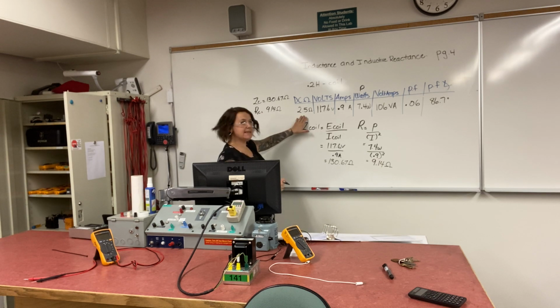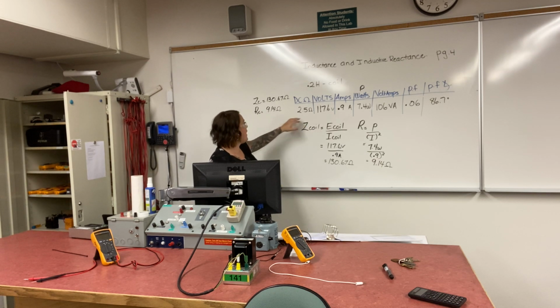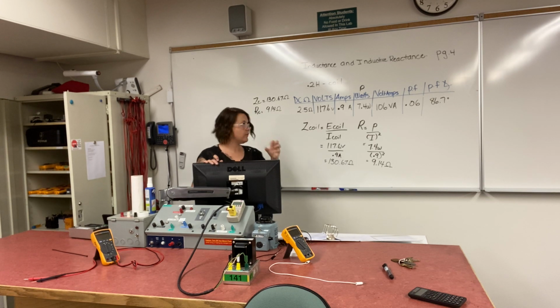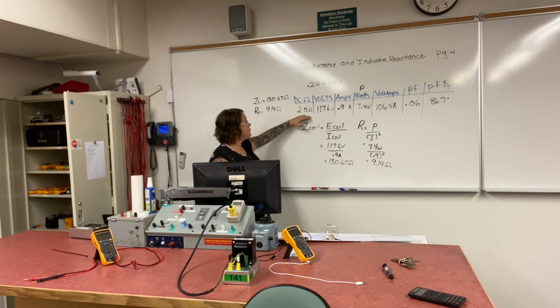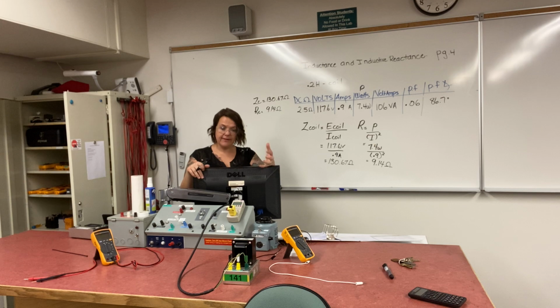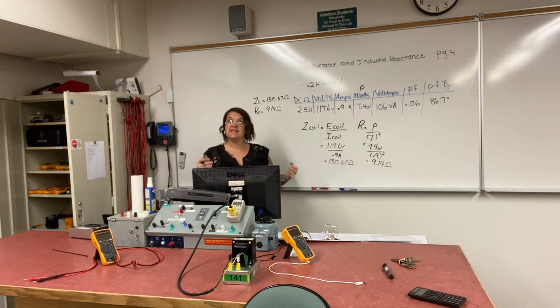So you can see that that's definitely a higher value than what we read through our multimeter in a disconnected component, right? And that's due to the supply being AC, right? So when we're reading across our coil with our multimeter, we are reading it from the voltage that's being supplied by the multimeter itself, which is internally fed, and it's giving you a DC voltage.